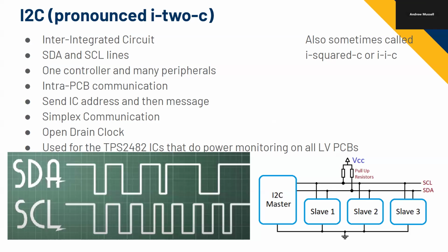How much extra? That's a very good question. That's actually a 151 midterm question. So the energy that's stored in a capacitor is equal to 1/2 capacitance times voltage squared. So you're putting that much energy into it and then getting rid of that much energy every time you charge. If you multiply that by your frequency, which is how many times you're doing that per second, then that would give you the total amount of power that you're dissipating.